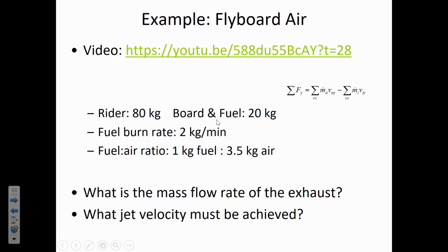If in the Flyboard the rider is 80 kilograms, the board and fuel is 20 kilograms, there's a total 100 kilograms of mass that's being supported by the momentum. And if you're burning 2 kilograms of fuel per minute, the fuel to air ratio is what's going to tell you the mass flow rate that's coming out of the boot, out of the control surfaces.